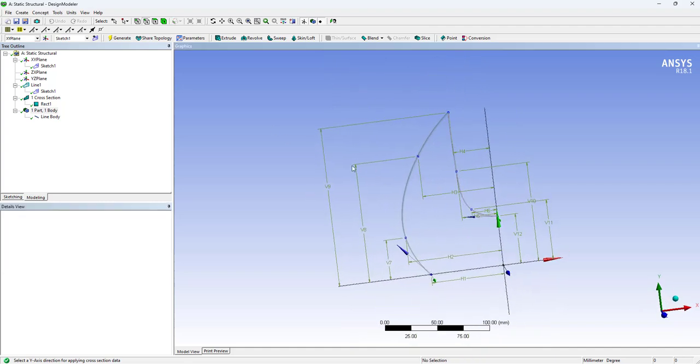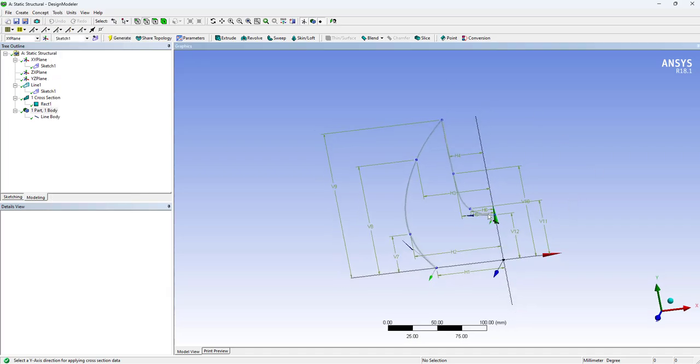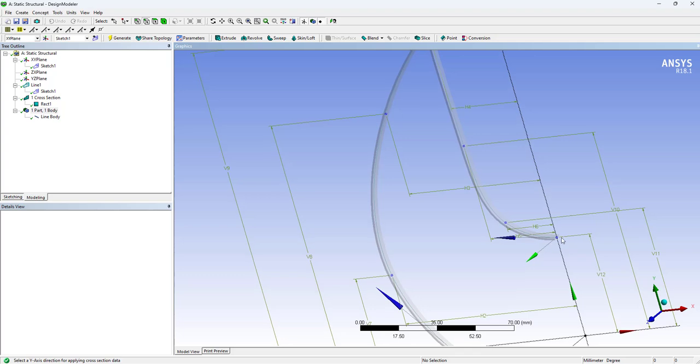One last thing about the line elements related to geometry is we cannot use the symmetry boundary condition here in the geometry for line elements. So we need to add some alternatives so that we have this symmetry in the model. For that, there is a combination of two boundary conditions. The first one is the rotation at the point where we want to specify the symmetry, and the second one is the displacement.